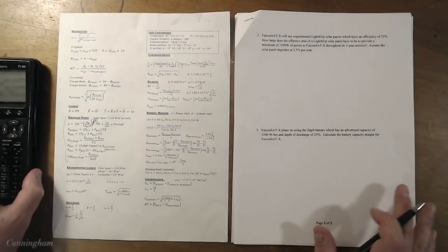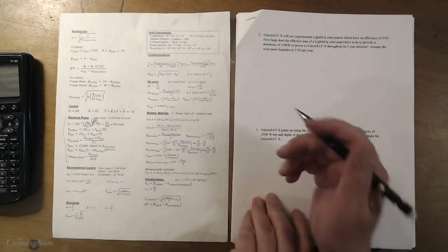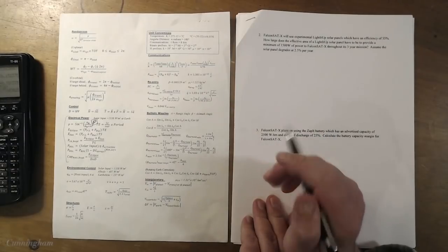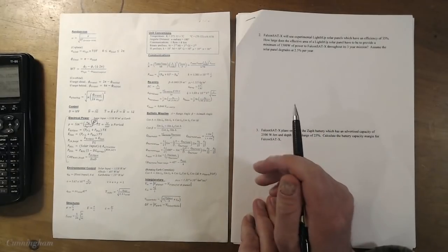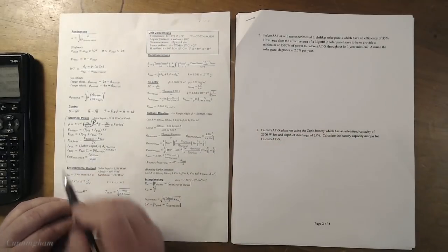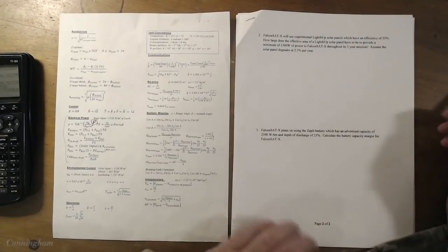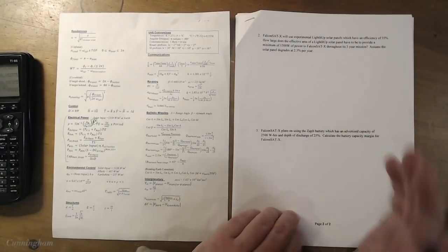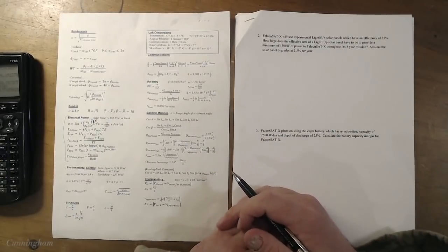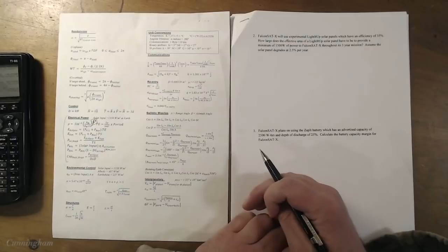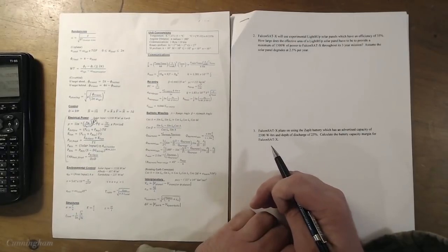Okay. Here we arrive at something that's kind of counterintuitive. To figure out what we need to build the satellite's solar panels for at the beginning of life, which is this P sub BOL on the equation sheet, we have to find out what it needs by the end of its life, right? After the solar panels have spent several years in space, degrading, possibly getting hit by tiny micrometeoroids or space junk, the performance of a solar panel becomes worse and worse over time.